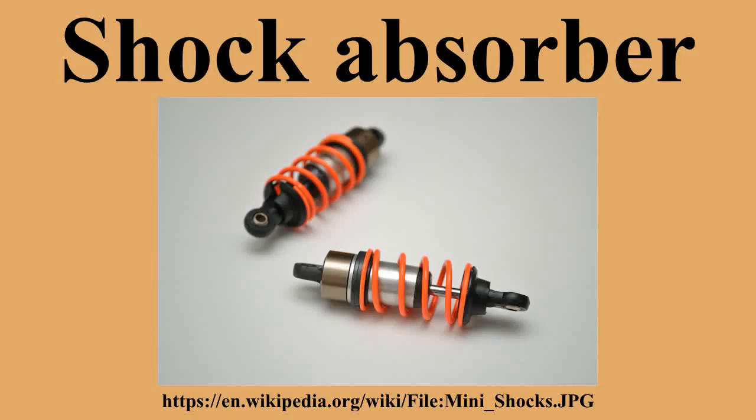Position-sensitive damping, often abbreviated simply as PSD. This design is another evolution of the twin-tube shock. In a PSD shock absorber, which still consists of two nested tubes and still contains nitrogen gas, a set of grooves has been added to the pressure tube.